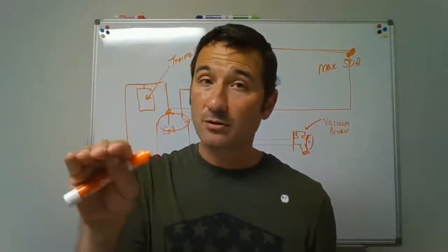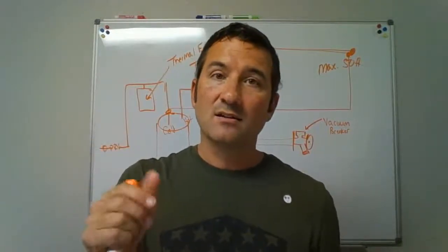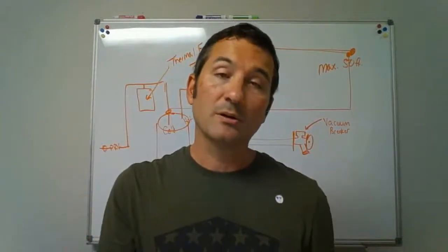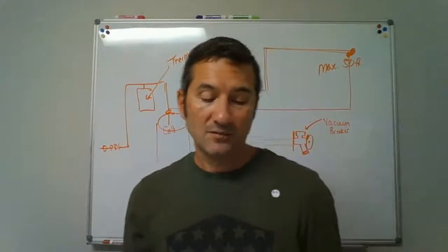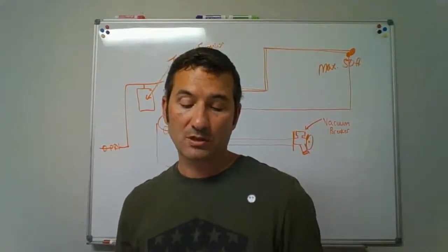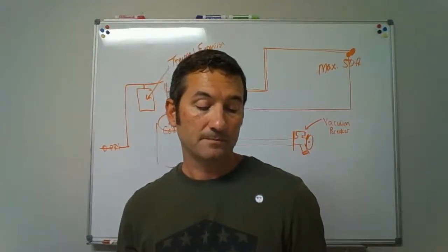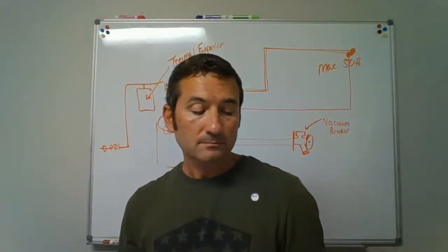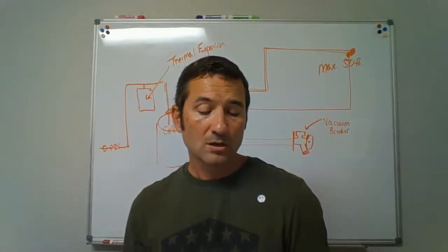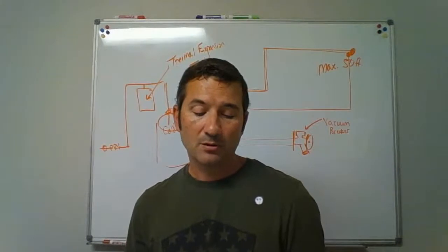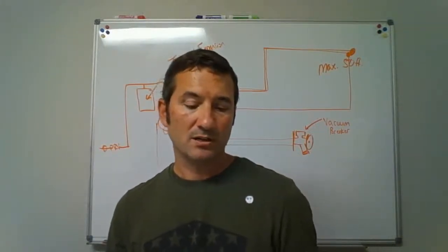And then under solder, look and see what the steps are to solder it. Does it say cut the pipe, ream the pipe, clean it, flux, and solder? Okay. If it has those things mentioned, then that would be a true statement. Okay. Question 10. You can attach copper tubing to galvanized steel pipe with a brass fitting. All right, is that true or false?